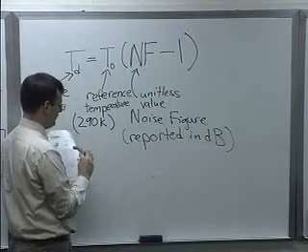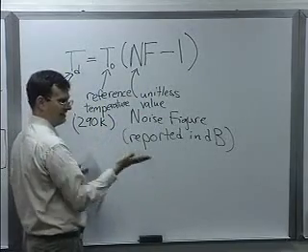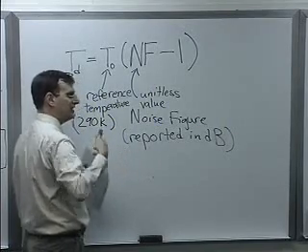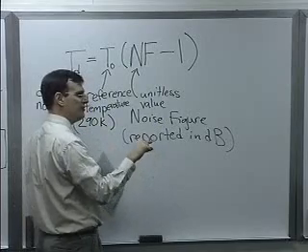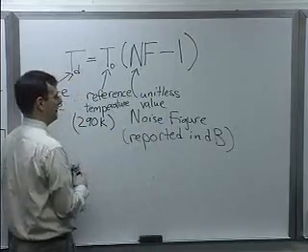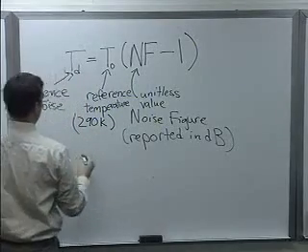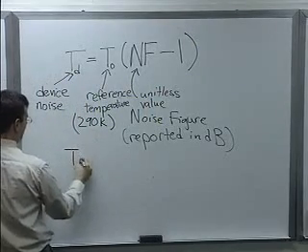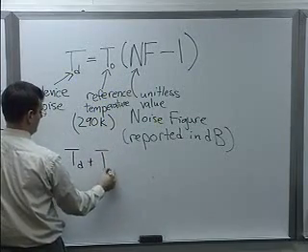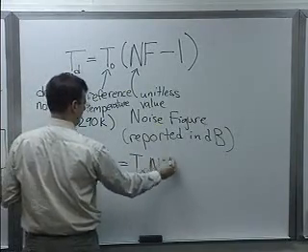The way that a noise figure measurement is defined is basically at 290 degrees Kelvin. I have 290 Kelvin of noise coming through my system. Noise figure you can think of as basically how that noise got magnified by the device temperature. If you were to rearrange this equation, you would get T sub D plus T sub naught equal to T sub naught times noise figure.